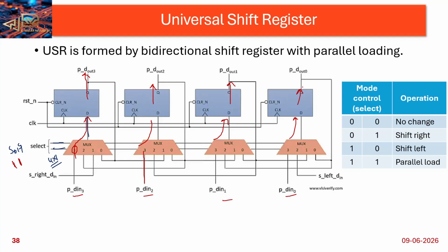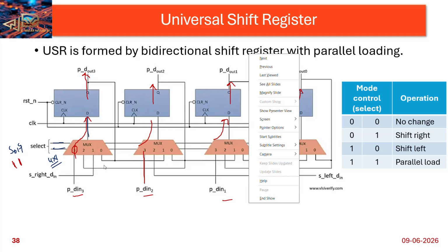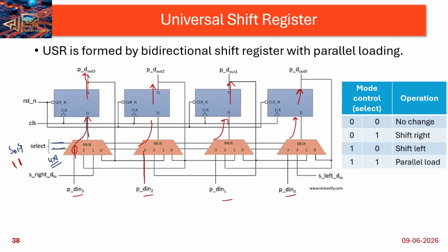Okay, and then shift register is serial in serial out. And then again, what is the second operation? See, second bit is connected to which one? So this is connected to this line D2. That means it is doing the left shift operation.